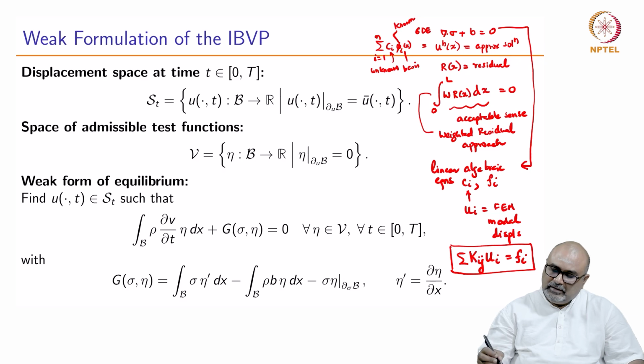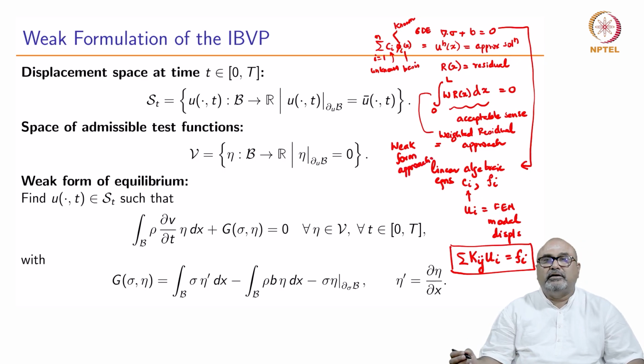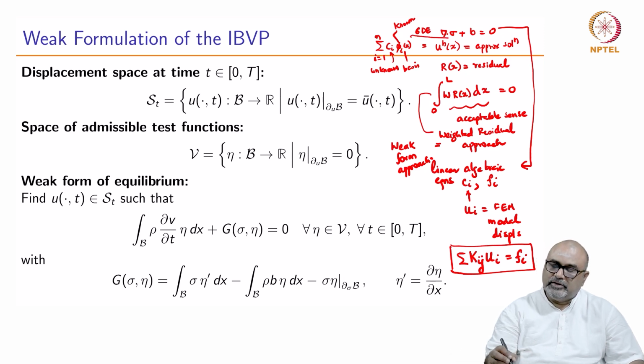The weighted residual approach is also called the weak form approach, which allows us to define approximations whose continuity requirements are one order less than the original differential equation.